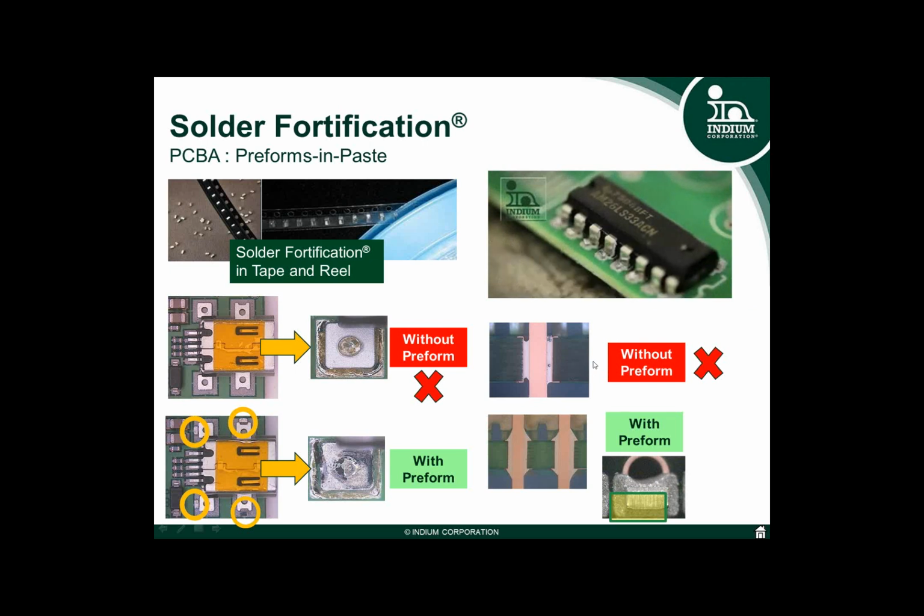Looking at the cross section of this device, you can see the benefit of adding that solder, because the fillet in the barrel in the top picture on the right-hand side is not showing a fillet. Then when we look to the bottom, you can see the fillet has been formed not only on the top side of the circuit, but actually on the bottom side as well, providing the good process indicators that quality inspectors are looking for.